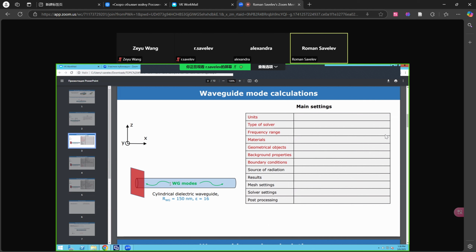In this case, we only need to consider a two-dimensional problem. You don't need to consider a really 3D problem. You can do it like in COMSOL, use a port. A port is a two-dimensional object. This is basically a cross-section of the waveguide, and then we find the modes of this port. So this is very similar to the numeric port of COMSOL.